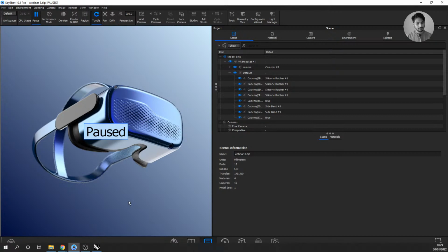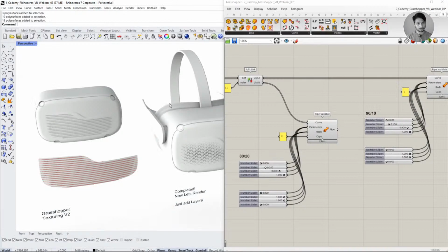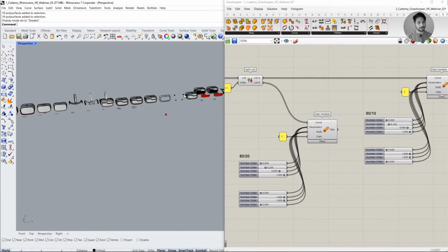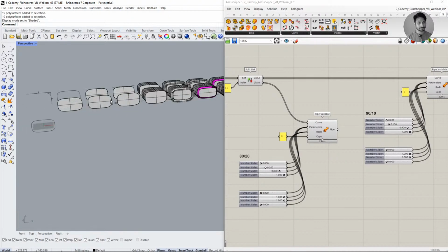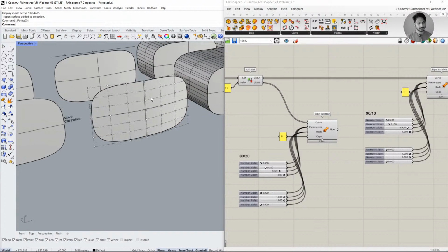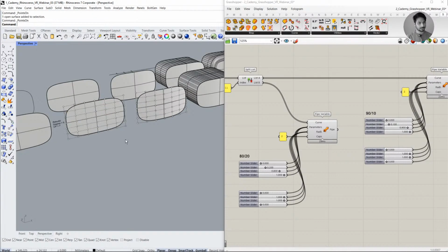All right, any more questions? Melissa asks, she tried to rebuild the surface but it didn't do anything. Did you confirm it by turning on the control points? So if you go back to the first surface, when you rebuild it, turn on the control points, and do you see this many control points, or do you just see something like this?